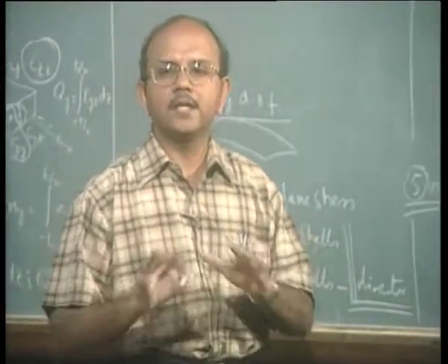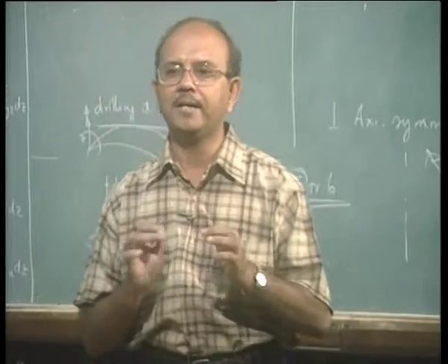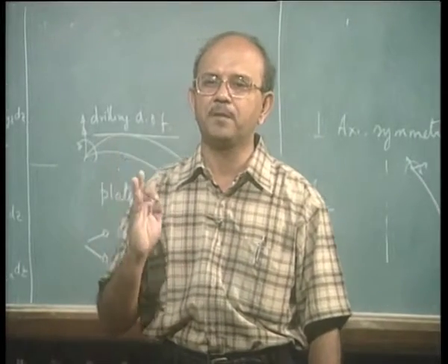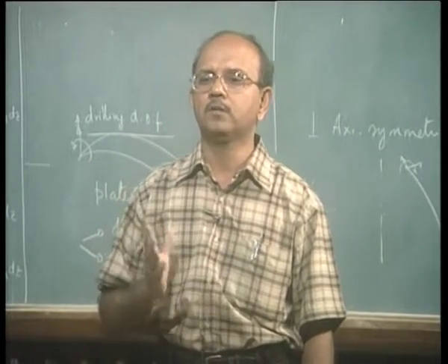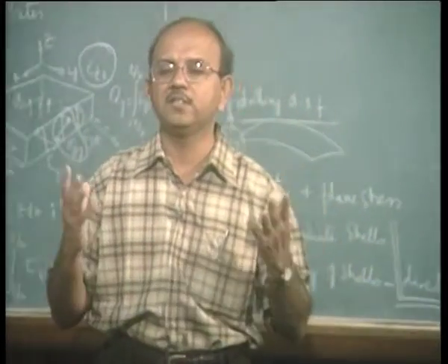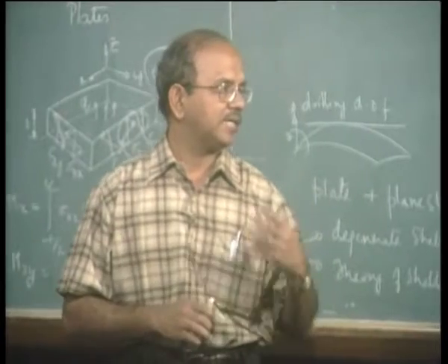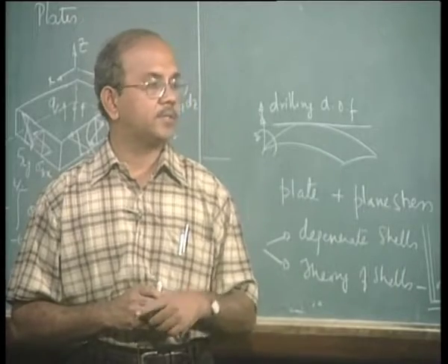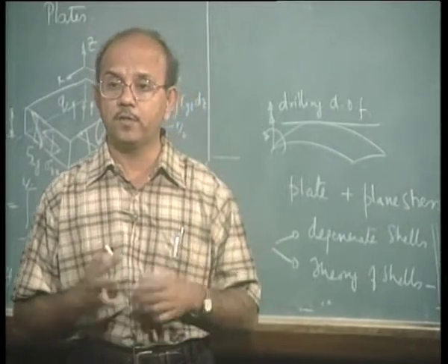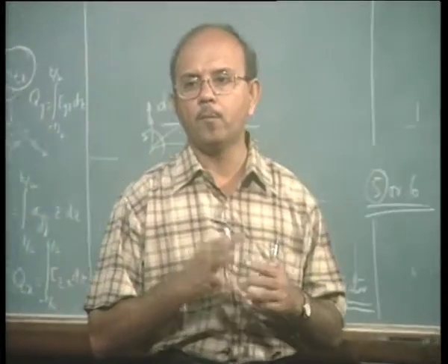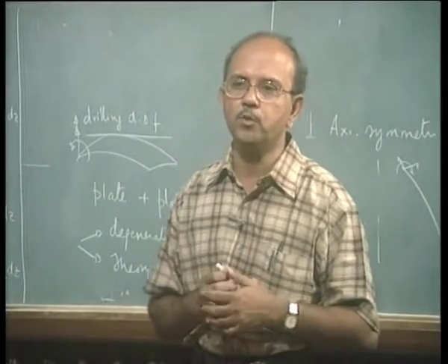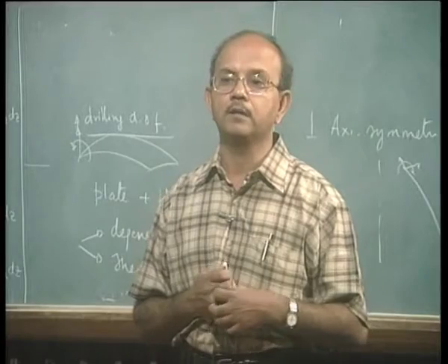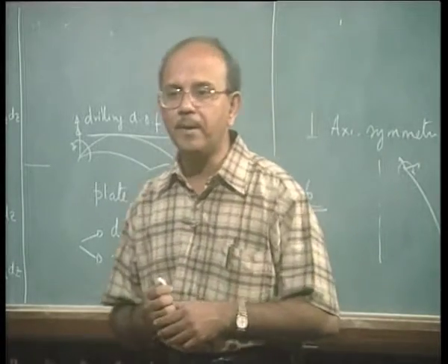I am sure that this kind of background would give you an idea, although I do not claim that we have gone into the depth and breadth of finite element, because it's vast. There are tens of thousands of papers that have been published in this field, and it's an ever growing field. There are still a lot of research issues that need to be tackled. Especially we have not seen much on explicit finite element analysis, which is becoming popular nowadays because of its ability to be used without problems like convergence in metal forming cases. For example, these are used for impact analysis and so on.